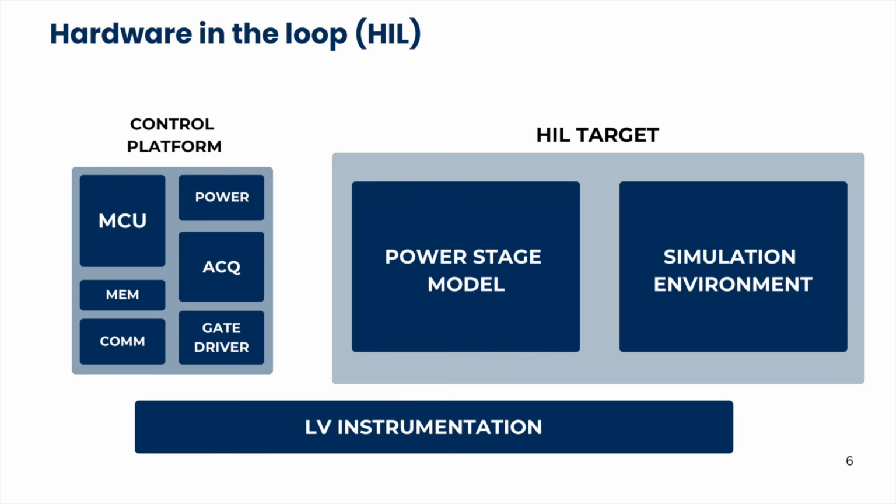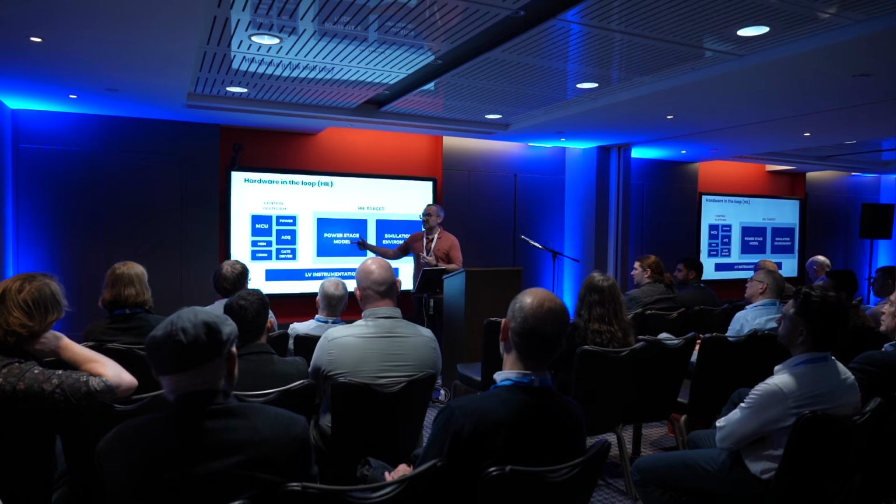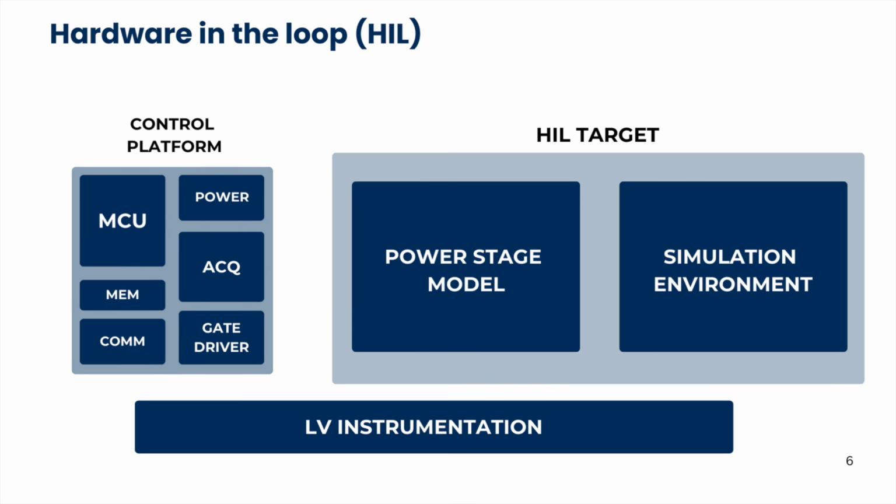If we are working with hardware in the loop, we will have the same control platform that we are using in our final product, but we are going to replace all the test benches with a model of the power stage. And also, since we are working with a mathematical model of the power stage, we don't need another power stage, another model of the power stages. For example, if this power stage is a solar inverter, if we want to simulate the grid conditions, that grid condition can be represented just with a sinusoidal wave.